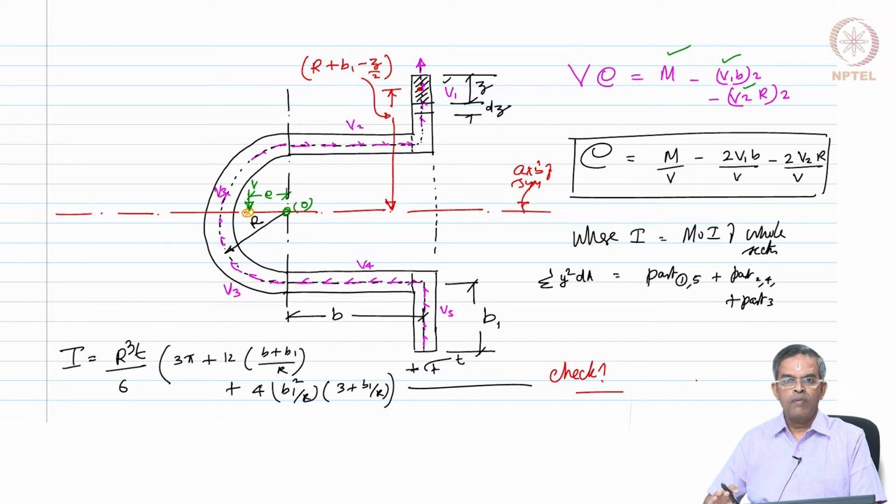So, when you have got form dominant designs where the geometric shapes are dependent on the functional requirements, obtaining shear center to check whether unsymmetric bending will be caused, whether twisting will happen, whether stability will be checked, all will become a prerequisite.